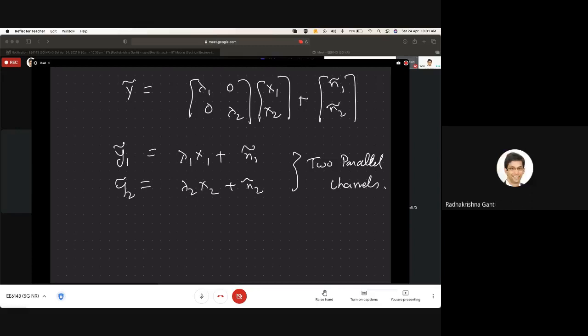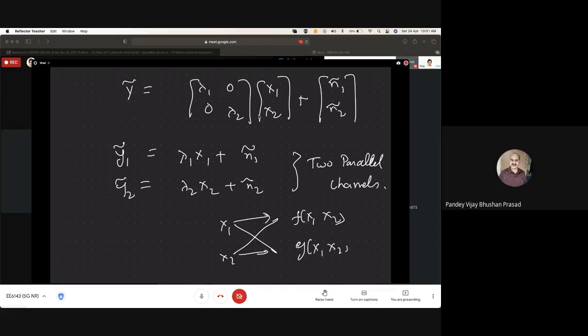Remember our original MIMO channel: you transmit x1, x2 and get some linear combination of x1 and x2, and similarly another linear combination. But now the interference is gone completely. So effectively what you got are two parallel channels.